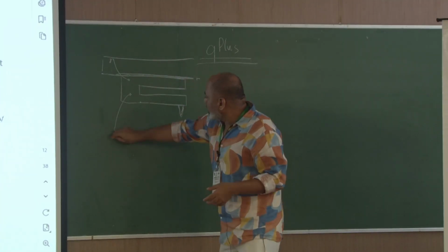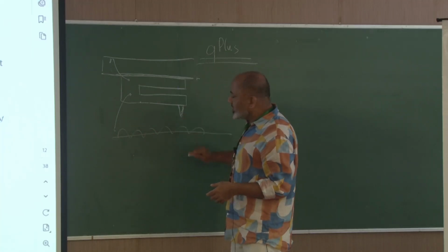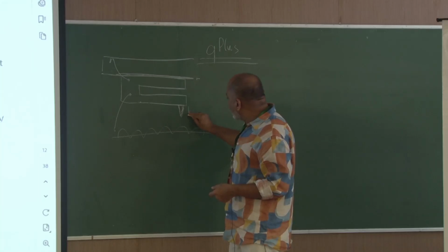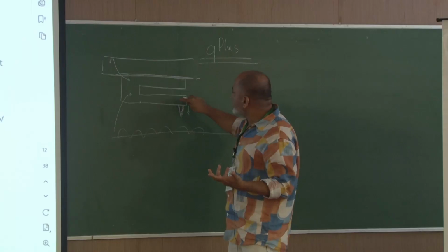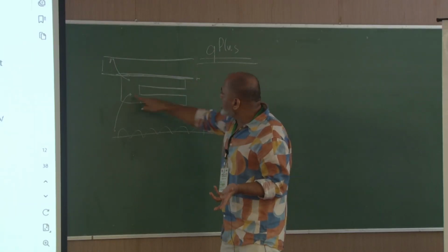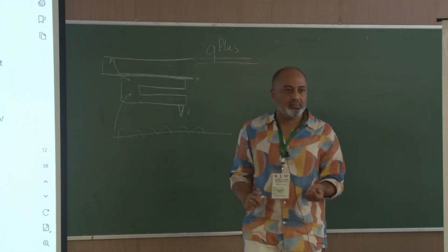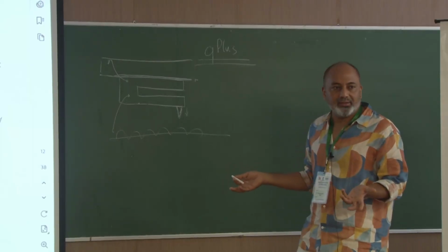The idea is, because of the substrate which is close there, if the tip comes into contact with the substrate, this guy bends. This bending is differential. This bends more than that. That guy doesn't bend at all, and this guy bends a little bit. This creates a current through this, and this is again using piezoelectricity to get the current.